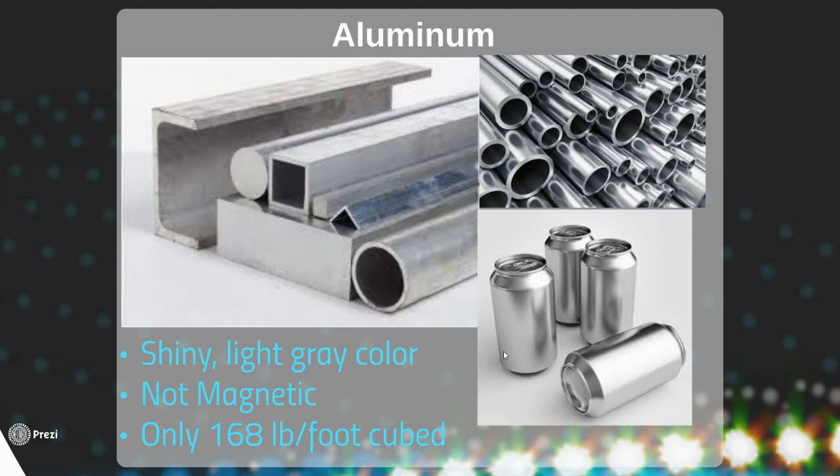All right. Aluminum. You can see here in the pictures it's actually a light gray, so it's a little bit brighter than your carbon steel and also your stainless steel, and it's also shiny too. So it's shiny like the stainless steel is as well. But see here, it's lighter, it's shinier. Okay, and it's not magnetic. So another big difference, not magnetic.